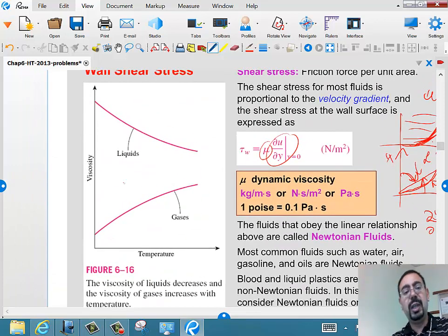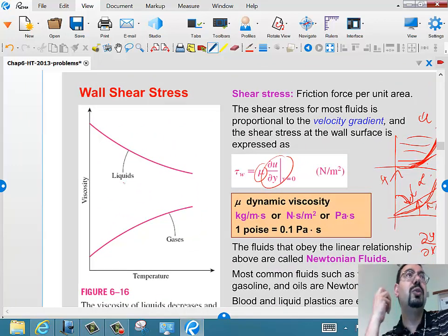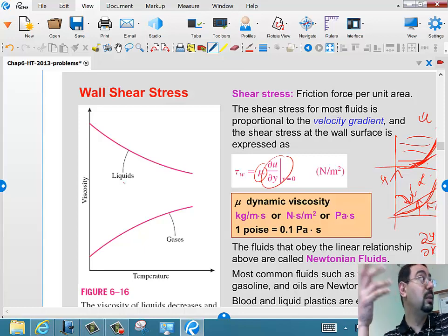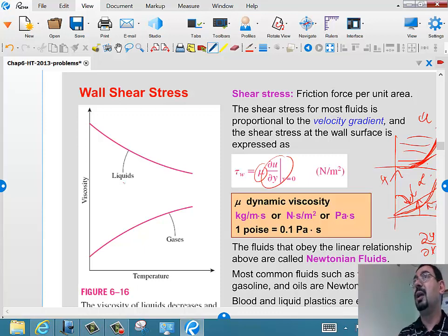Right? So he's also saying that we think of viscosity as being constant all the time, like what's the viscosity of oil, what's the viscosity of honey, what's the viscosity of water, but it's actually a function of temperature, right? The viscosity is a function of temperature. That's why they sometimes heat very viscous oil to let it go through the boiler or the furnace. It's very hard to pump it when it's cold, but when you heat it a little bit, it gets easier. And in the oil industry, when they have this very sticky, heavy oil, how can they get the oil to come up?